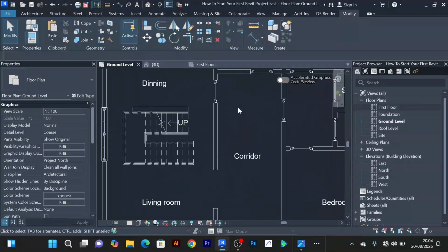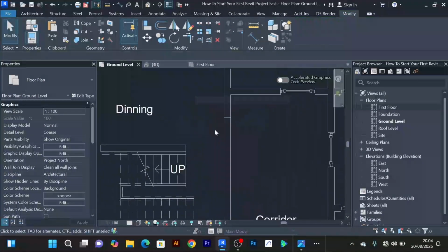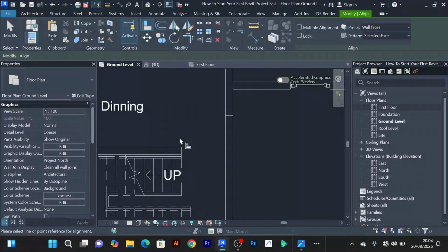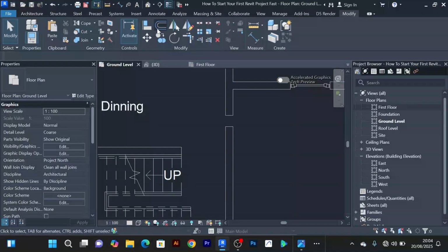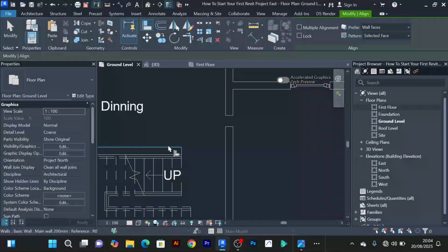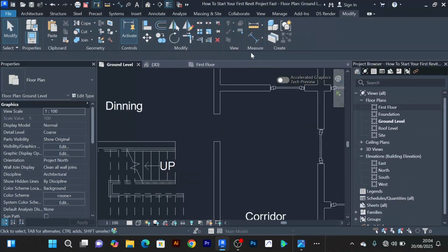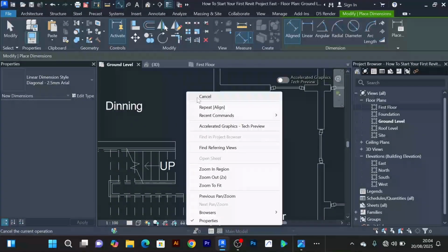Now I think this door, I will remove it. I'll split this wall here. Instead of that door, I'll just align this with the line tool. Let me first drag it a little bit here before I can align it. Pick the line tool, you align like that, so that this can also be an open space. Let me see the distance, 850.